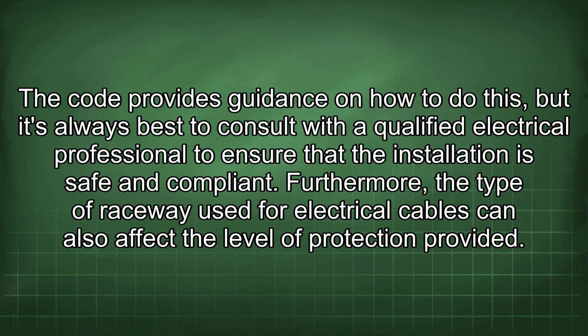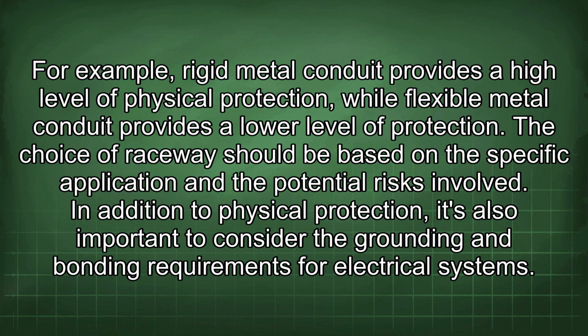Furthermore, the type of raceway used for electrical cables can also affect the level of protection provided. For example, rigid metal conduit provides a higher level of physical protection, while flexible metal conduit provides a lower level of protection. The choice of raceway should be based on the specific application and the potential risks involved.